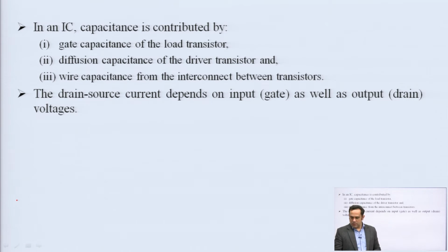So, the solution of this differential equation is basically what is known as transient analysis or transient response, and this response provides us with a value of propagation delay. In an integrated circuit, capacitance can be obtained from different sources. It may be present because of the way the IC is fabricated, the layers it has, the material it uses, or the way the interconnects are connected.